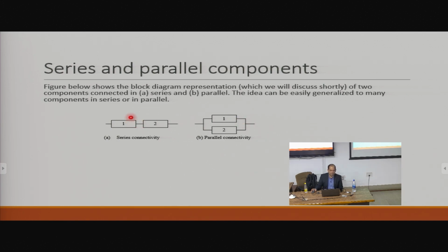So if you think of it as two generators working in parallel, one is enough to support the load, then this is a very reliable system. And then here we have loss of reliability because it's a series system, because two things have to work. Let's say you have a generator and then you have a voltage converter. Okay, if either one of those fails, then you don't have power.